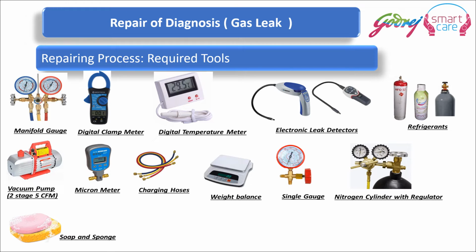For this process, you would require the tools shown in this diagram: manifold gauge, digital clamp meter, digital temperature meter, electronic leak detectors. We need refrigerants. We need a good vacuum pump, two-stage, and at least 5 CFM for air conditioners. A pump of less than 5 CFM two-stage is not a good or healthy vacuum for air conditioning units. Then the best meter to check vacuum is the micron meter.